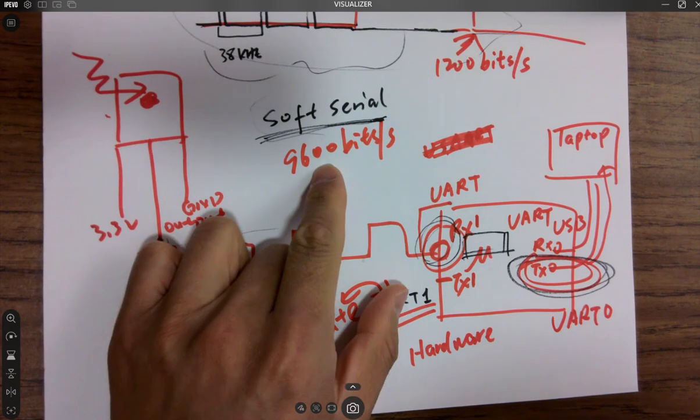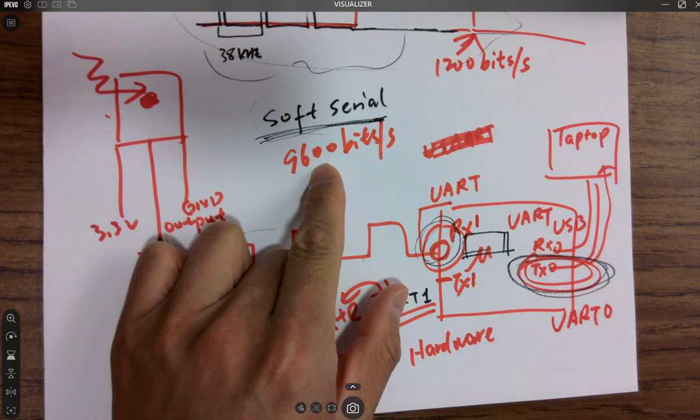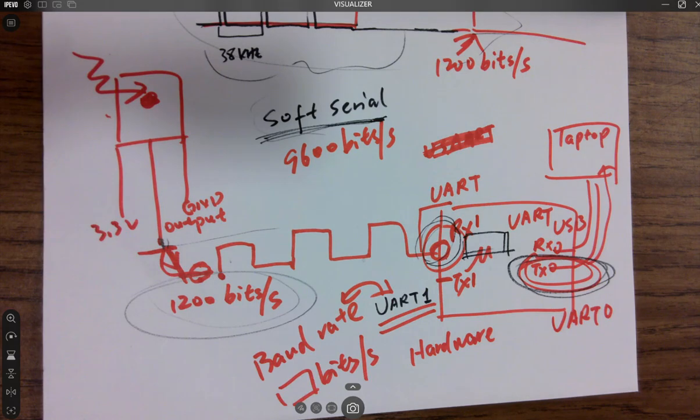And you can pick up faster rates. There are different options. So in your serial begin, you can choose faster ones, slower ones, doesn't matter. But when you change the baud rate in your code, you have to change that in your serial monitor. There's a little option at the bottom. You have to change that one accordingly. Otherwise, it's going to report really weird symbols to the serial monitor.